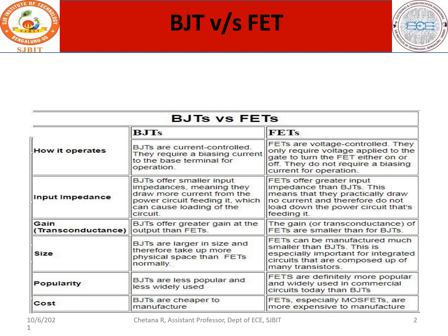So if you check with your analog electronics, the entire operation of the BJT characteristics is controlled with the help of current. Like it can be the base current or the collector current or the emitter current. So basically they are current control devices. And when you look into FETs, you can also observe they are voltage control devices. The voltage is dominant in FET. For example, VDS or VGS, these are the voltages with respect to the drain and source and gate and source, and therefore it is a voltage controlled device.